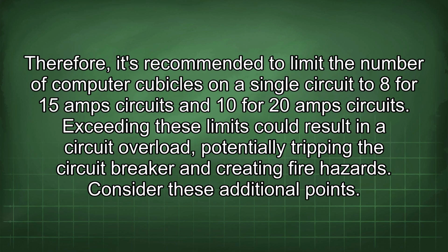Therefore, it's recommended to limit the number of computer cubicles on a single circuit to 8 for 15 amp circuits and 10 for 20 amp circuits. Exceeding these limits could result in a circuit overload, potentially tripping the circuit breaker and creating fire hazards.